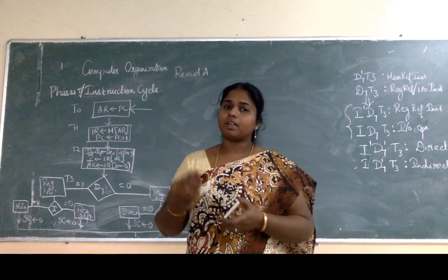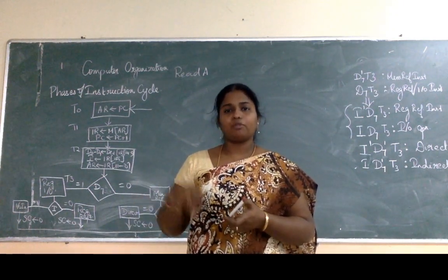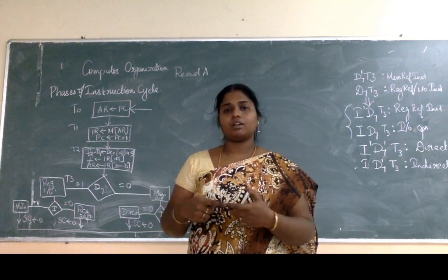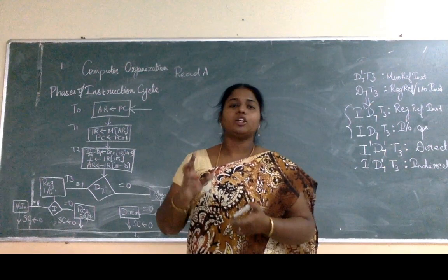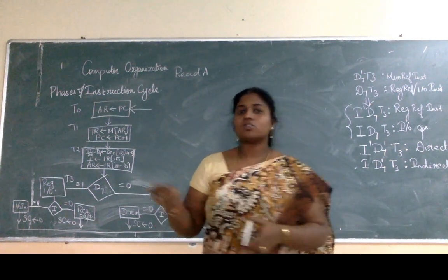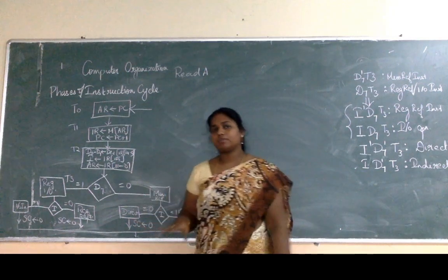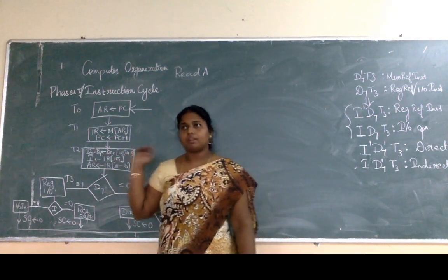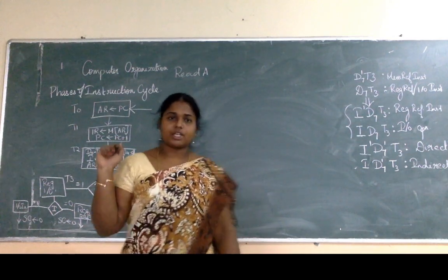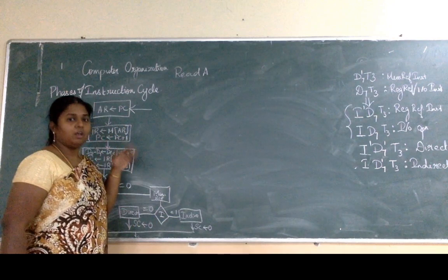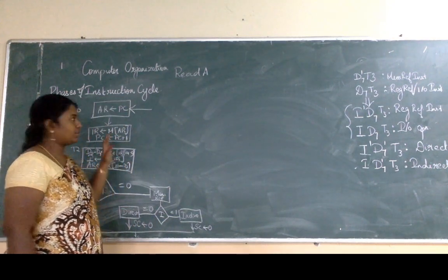Every time an instruction is executed, before timing cycle T15, the sequence counter is cleared to indicate that it should start counting from T0 once again. Time cycles T0 to T15 can be used for instruction execution, and T0 to T2 remain the same for all types of instructions.